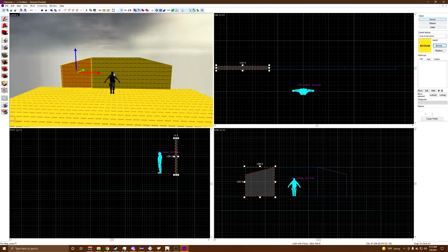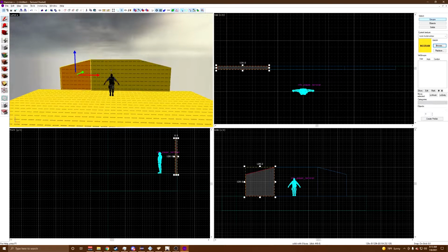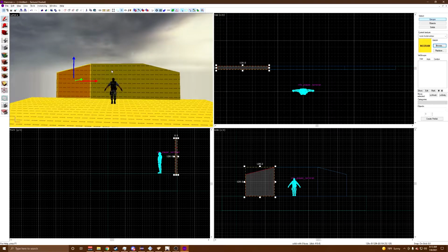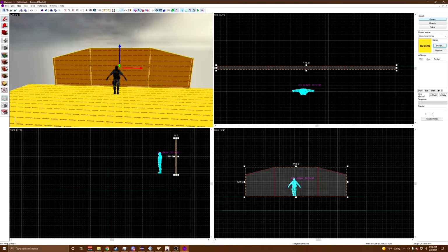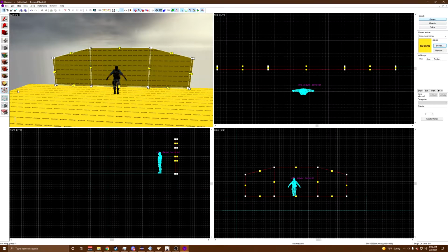As a general rule of thumb, whenever using these 2 tools, always make sure that the ending vertices of your brush always align on the grid, and if they don't, know why they don't align. We'll get a good example of vertices that don't align on the grid whenever we get into displacements later on.